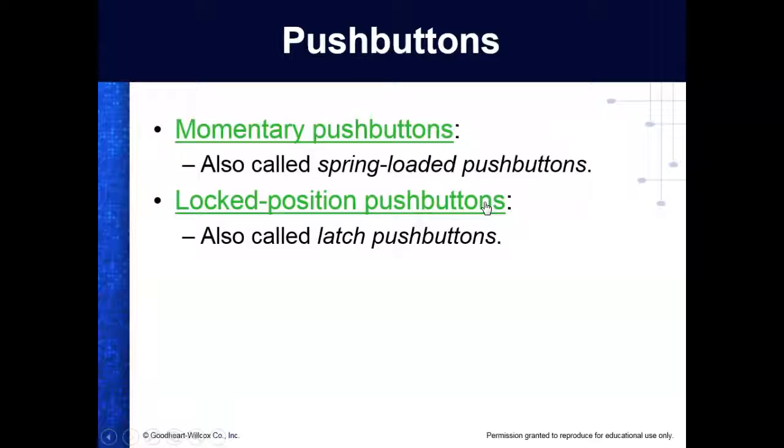Then we have latching push buttons. A lot of your e-stop buttons are latching push buttons. Ours are not, so y'all don't have them. These e-stop buttons up here, on these disconnects right here, are latching. I'm not sure about the blue ones though. But some e-stop buttons are not. These are latching, which means you push them in, they latch down, and you have to push it back up. Pull them back up. A lot of your e-stop buttons, by the way, you actually have to turn them and pull them out. So that means you can't accidentally, you have to deliberately pull them out, right?